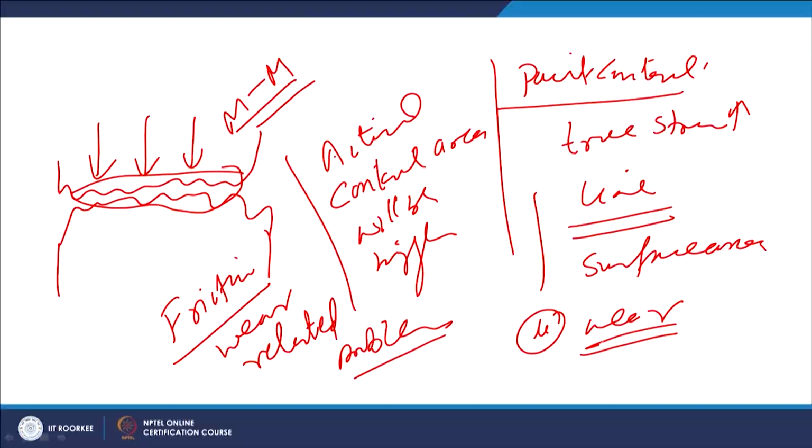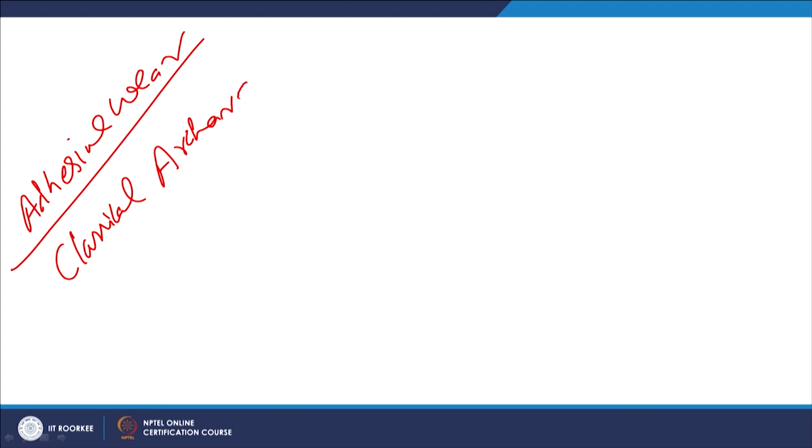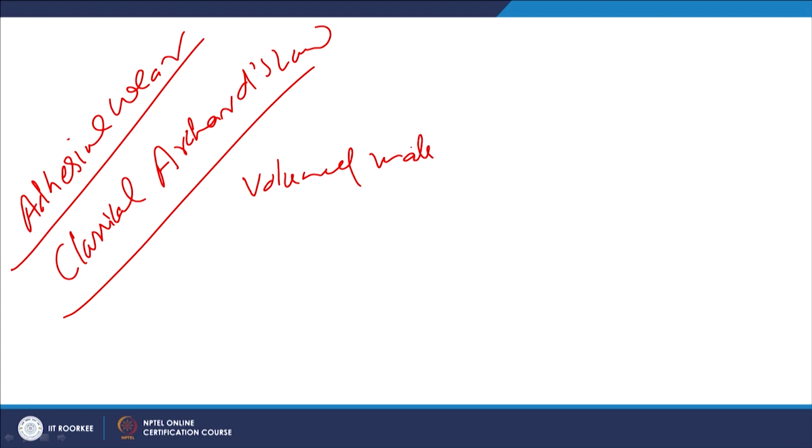In case of the ball bearing and roller bearing, we know that since the contact area is very less and the lubrication is very effective, this helps in having the relative movement at a very low wear rate and with very low frictional effects. So, adhesive wear is represented through one of the very classical Archard's law on the adhesive wear, and according to this what it says, that volume of the material lost by